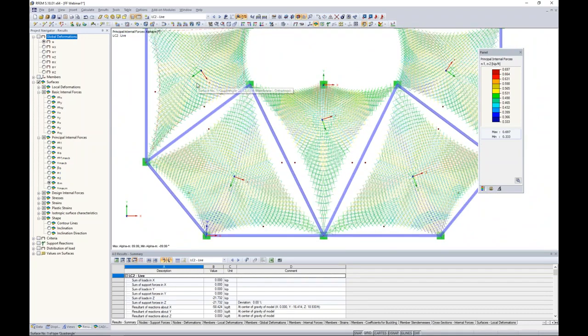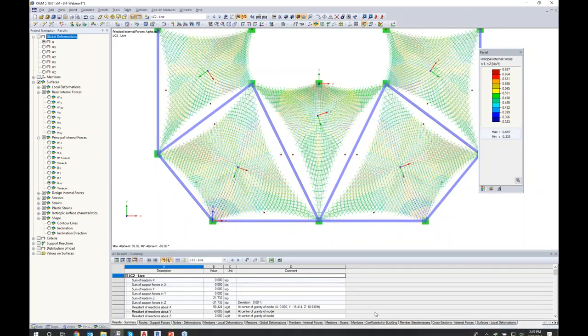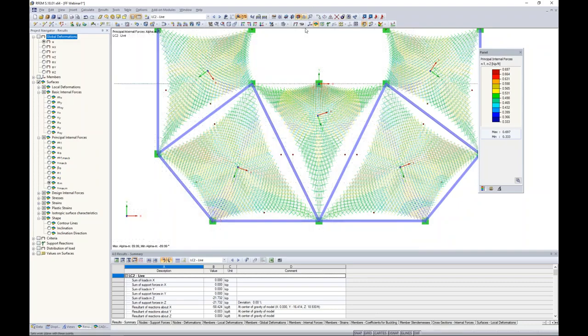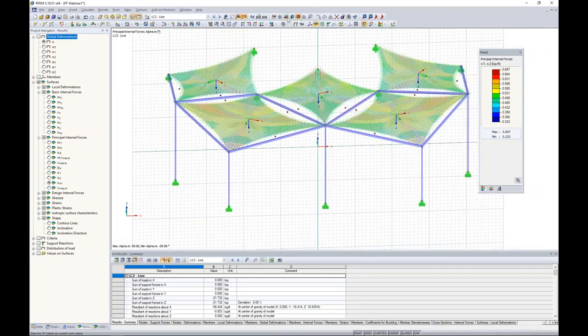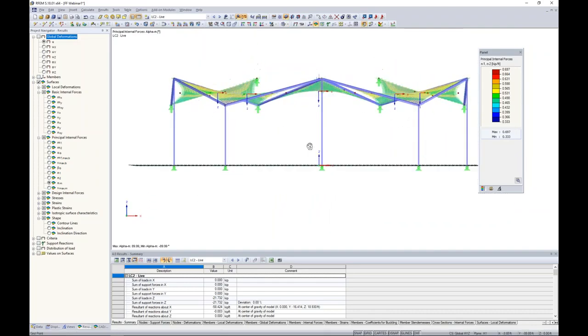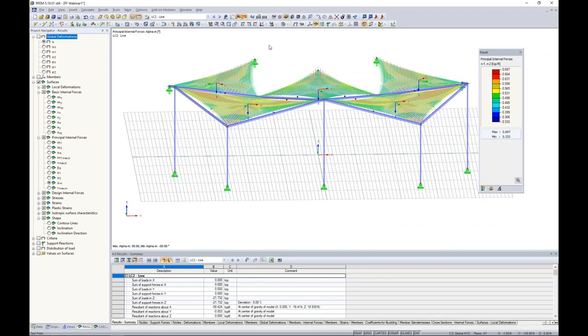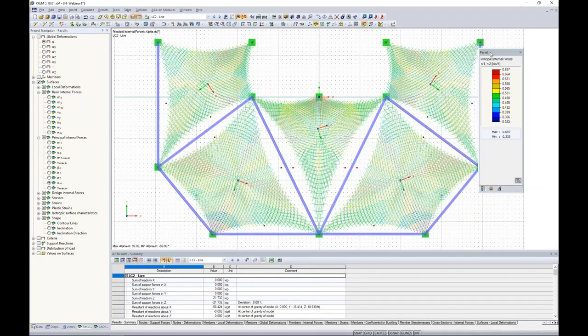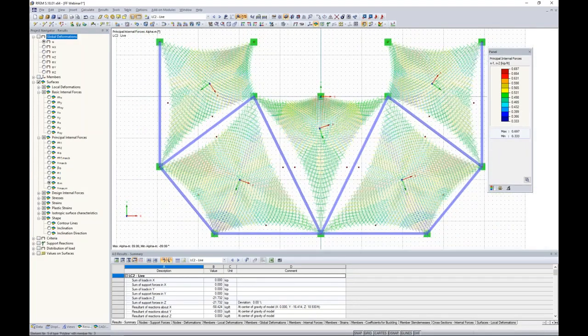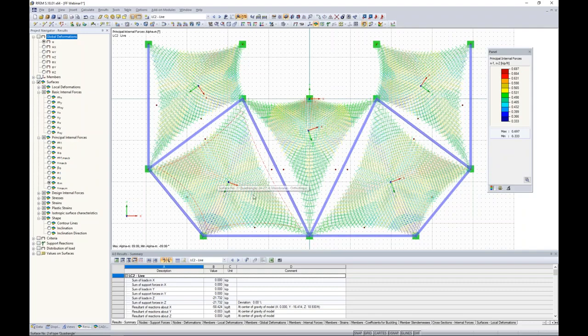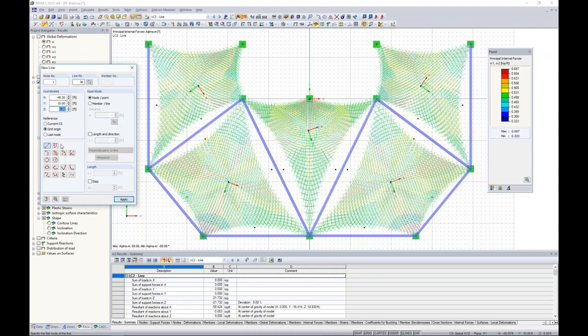So how do we orient our local axes of these members to make sure that they're taking the high tensile forces? How we do this is I'm going to turn back on my grid down at the bottom, and I'm going to uncheck the option for my user defined grid, and we change this in the XY plane. So now we're just looking at that drawing grid at the bottom of our structure. We probably want to take a screenshot here, or maybe we can just approximately remember which way these high tensile forces are spanning, because once we draw a new line element here, which is what I'm about to do, the program's going to suggest that I have to clear my results in order to change any type of the geometry within the model. That's not a problem.